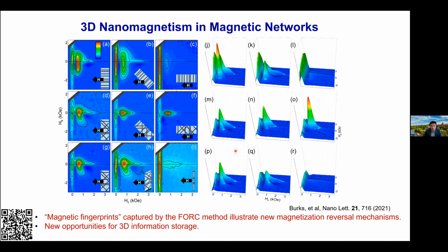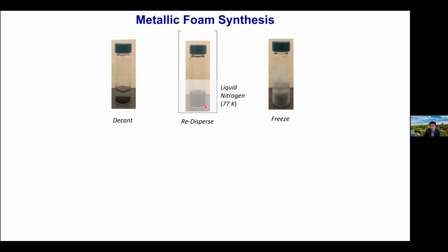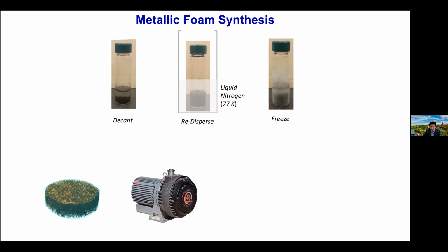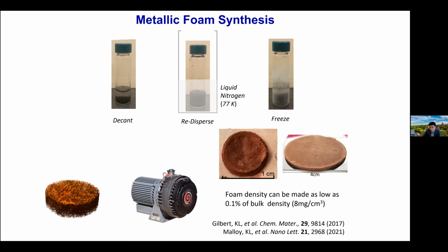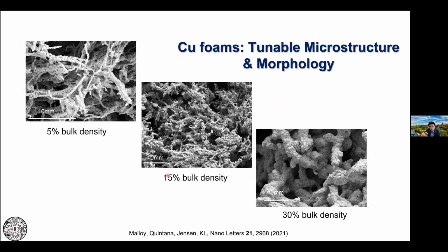So we started out trying to see if we can use the metal nanowires and convert them into foams and use them for filtration. We start out using the same process as we used to make the nanowire network. We grow the nanowires in templates, then we harvest them out. Then we mix nanowires with water and freeze dry it. Afterwards, we sublimate the ice, and this leads to freestanding metal foams. And we go through an additional sintering process to reinforce the structure.